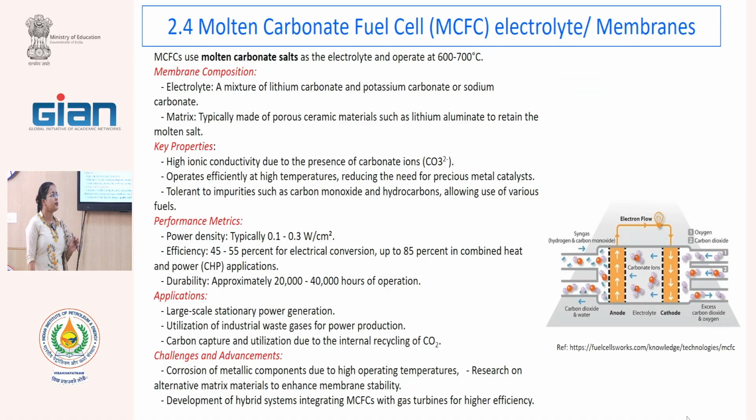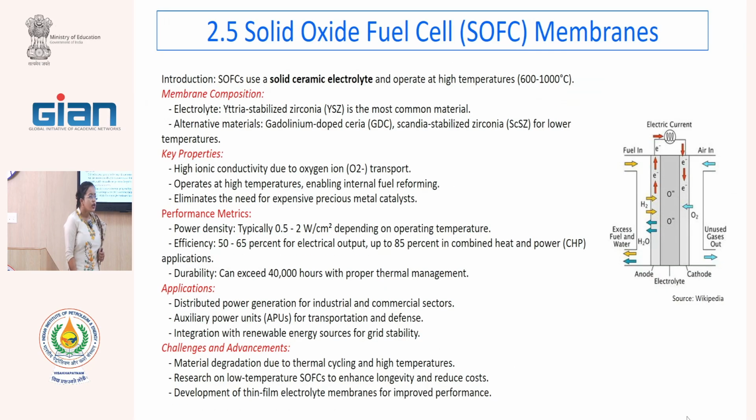They will give a lot of power, and you can even pair it with carbon capture to make the process more economical and more sustainable. So these are some of the MCFC features, but keep in mind that the membranes we use are metallic carbonate in nature and have to be in a liquid or molten form to make it work.